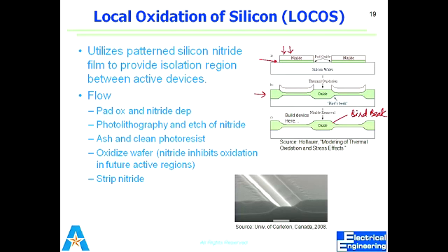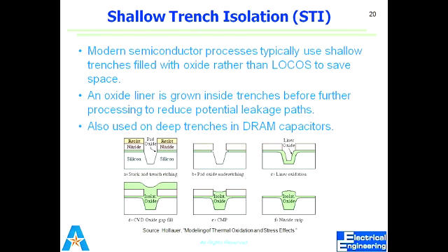So the active area should be at least 2 times the thickness of the field oxide. If the field oxide is 500, it encroaches 500 from this side, 500 nanometer from this side. If the active area is 1 micrometer, which is equal to 2 times the field oxide thickness, it means nothing is left, there would be no active area. So my active area should be large enough. We have not mentioned it on this slide, but the active area should be large to avoid this LOCOS problem.